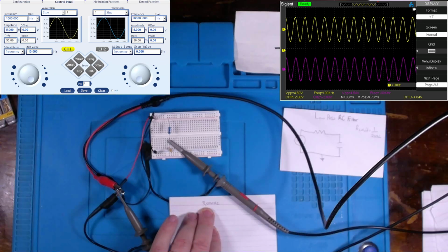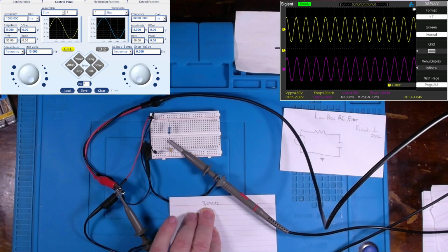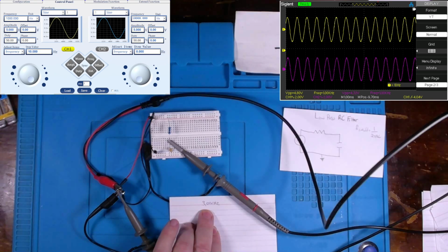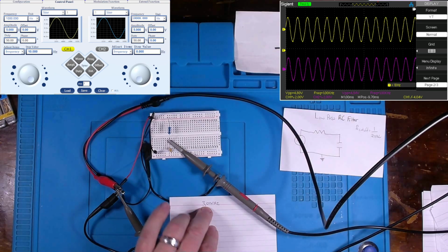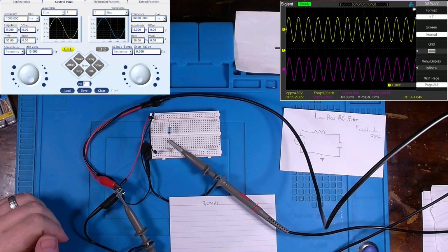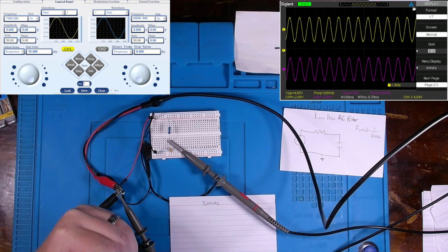Typical transmit bandwidth is between 300 to 3K hertz. So I just chose 3,000 hertz as where I wanted my upper limit to be, and everything beyond it to attenuate. Everything below 3,000 hertz to pass through my circuit.